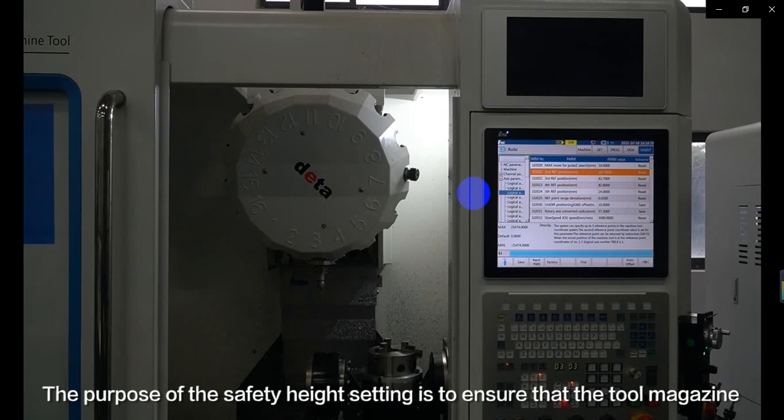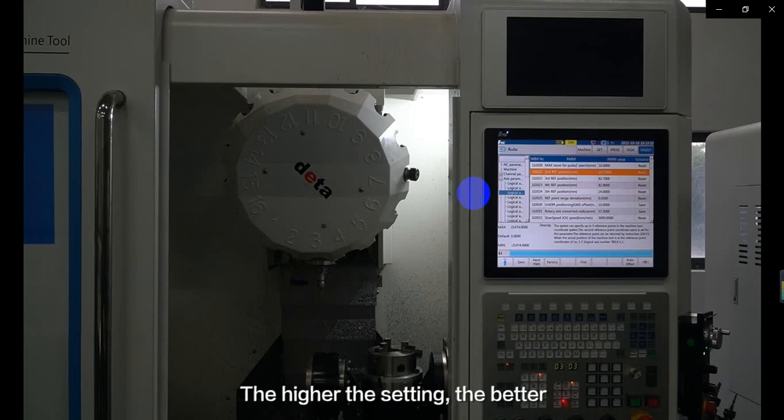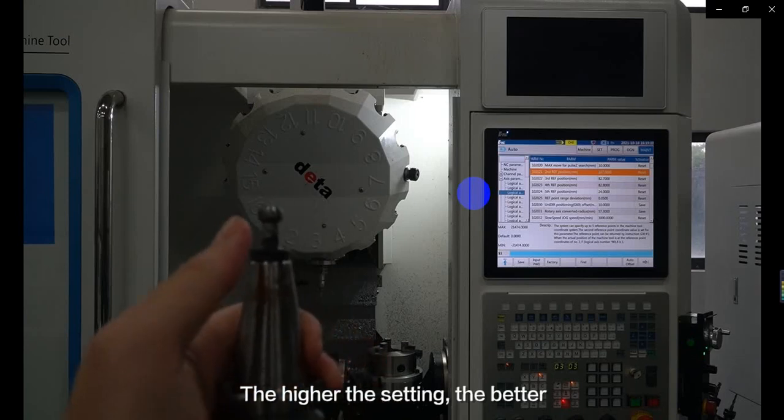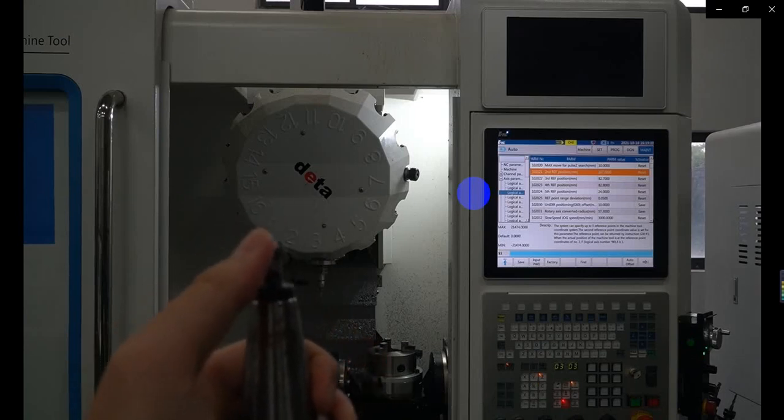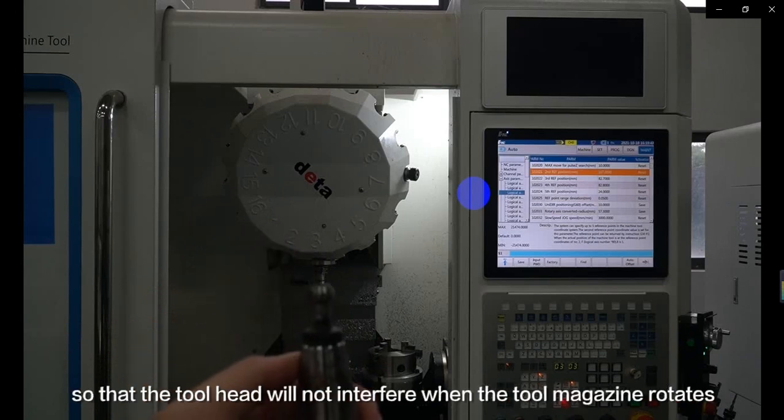The purpose of the safety height setting is to ensure that the tool magazine will not collide with the tool head or the spindle during the rotation. The higher the setting is, the better. The position of the tool head should be lower than the spindle stay point, so that the tool head will not interfere when the tool magazine rotates.